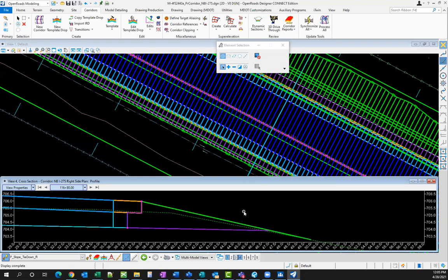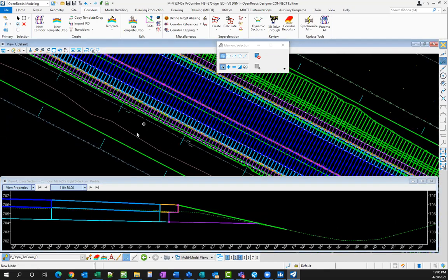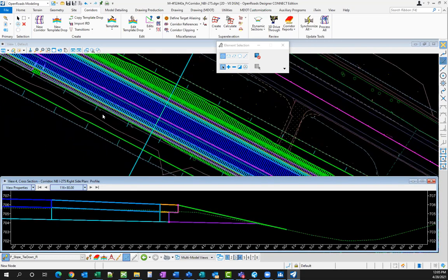But I'll just pick an offset that's slightly outside of where I want it to daylight to, and whatever my slope is, my slope is. Obviously, you still need to go through and check things, make sure it's not getting too steep. There might be some instances where this tie line isn't going to work, but a lot of times that's my methodology for end conditions. I just have one solution that I'll control with a parametric constraint, and I'll have this forced slope tie line for any kind of unique areas.